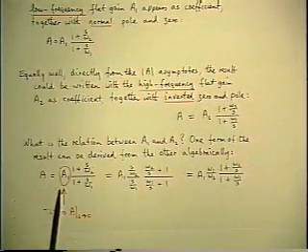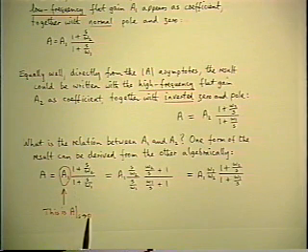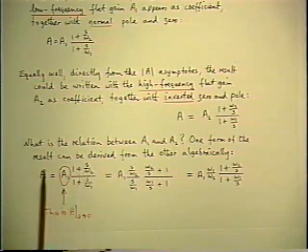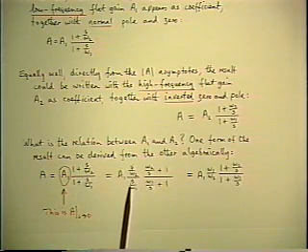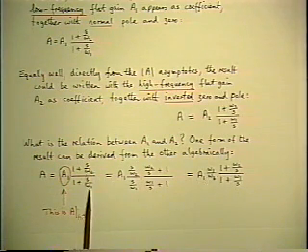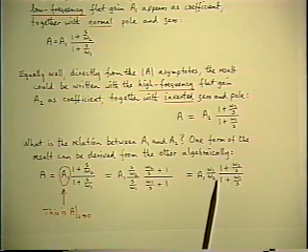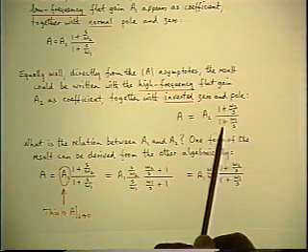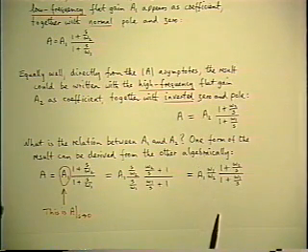If we start with the original expression we had this time, the interpretation of the A1 is it is the gain as frequency goes to 0. And algebraically, we can pull out S over omega 1 from the denominator, S over omega 2 from the numerator. The S's cancel, collect the terms together, and you get a new coefficient in front, and the pole and the 0 have now become inverted. And if you compare this algebraic result with the one that you would get by writing the same result by looking at the diagram, you see that there has to be an equivalence between these two flat gain coefficients. They have to be the same,